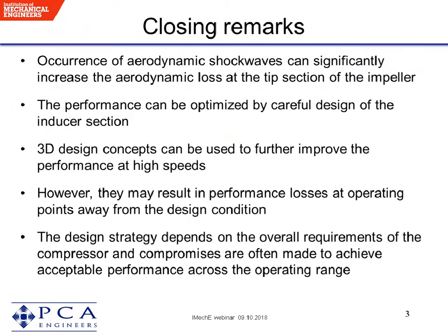I'll go to the second question. Are there any best practice methods to reduce the noise of high-speed centrifugal compressors? Mick, I can try to answer that. Yeah, thank you. So the noise in high-speed impellers is very much affected by the strength of the shock, and so the general approach to optimize the efficiency by reducing the strength of the shock also is beneficial in reducing the noise.